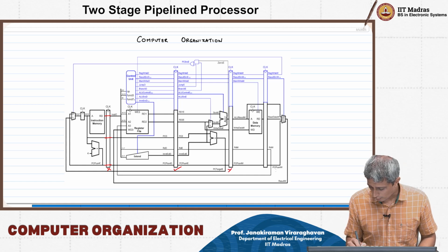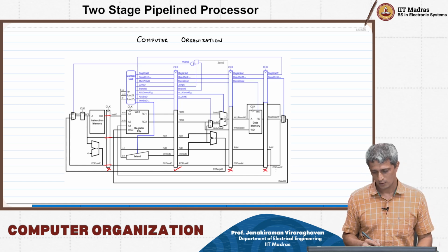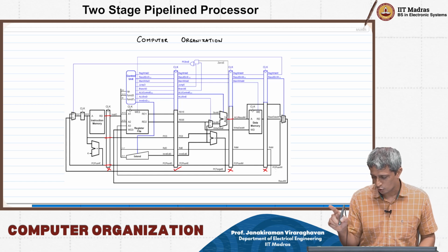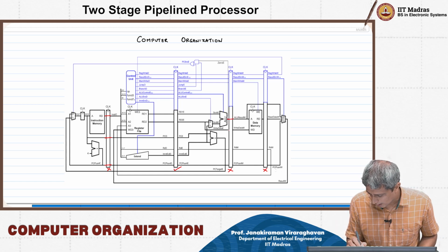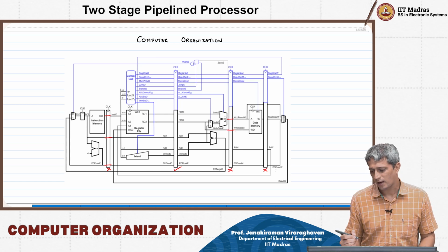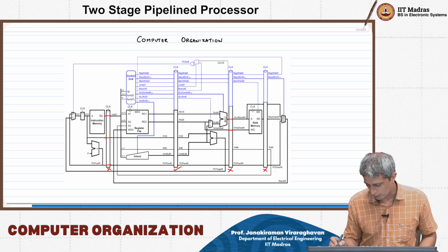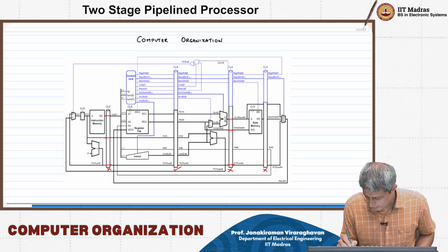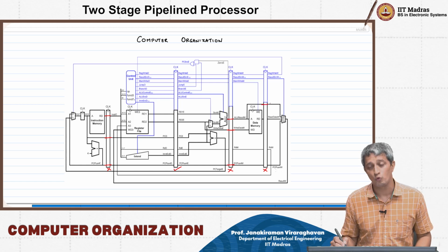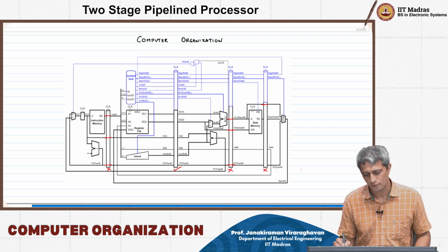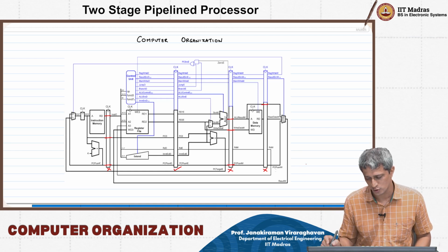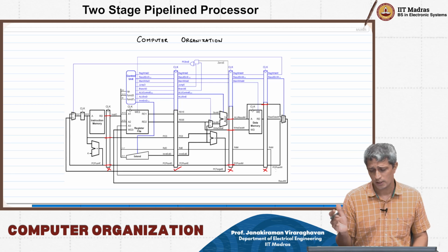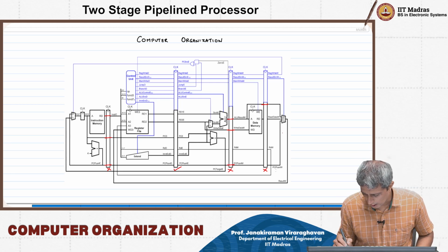Then I am going to get rid of both these flip-flops. Which means that the ALU result will simply bypass the flip-flop, go through directly as ALU result E or ALU result M. Write data E will come out like this. Okay, likewise this also will bypass, right? Then this signal will go through because you're skipping that flip-flop, so the ALU result can bypass and just go in as ALU result M or ALU result E actually, right? Because that's all we have out there.